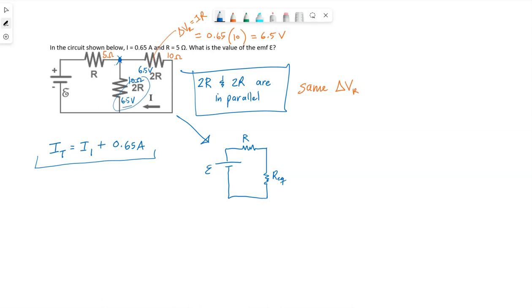I know it has 6.5 volts. So the I1, the current flowing through it, using the same equation but solving for I, we know current is potential difference over R for a resistor. So 6.5 divided by 10. I1 is also 0.65 volts. Sorry, 6.5. Oh dear. 0.65 amps.